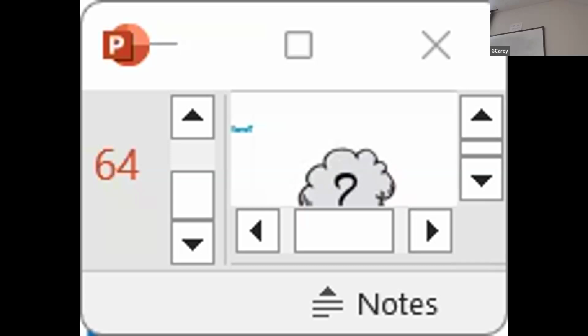And these will just be some visuals, variable primary. I don't have primary-secondary here with boiler pumps and distribution pumps. I'm using this pump to provide flow through my boiler plant as well as through my terminals. And I've got maybe some type of VFD drive with some remote DP sensor that has that control head that says, hey, I need a minimum of 15 feet or 20 feet or whatever that number is. So as I'm ramping this pump down, don't go below, maintain that minimum 20-foot head loss to ensure proper flow through the coil and the control valve.